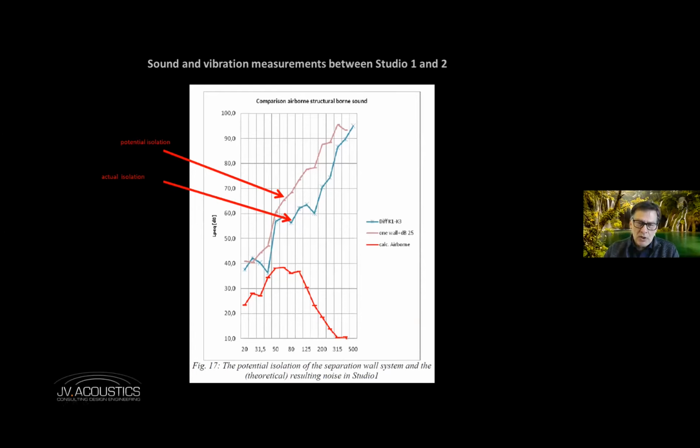At the same time with these acceleration sensors, we checked the secondary airborne sound, so the airborne sound which comes from the vibrating surfaces, like for example the floor and the room within a room construction which stood on that floor. And the spectrum of these vibrations showed us pretty well that this was a structure-borne problem which we had to solve. And therefore, it was not just repairing a hole or a duct or something like that.